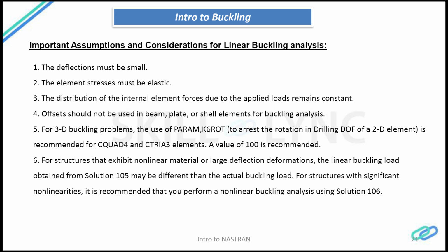And to that degree of freedom, you should try to give some stiffness value, which is minimum, a value of 100 is recommended. So this command, which is in the Nastran BDF, PARAM K6ROT 100, would solve that problem. That is again a limitation of the tool that we have to watch for.